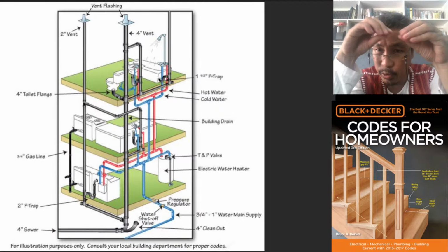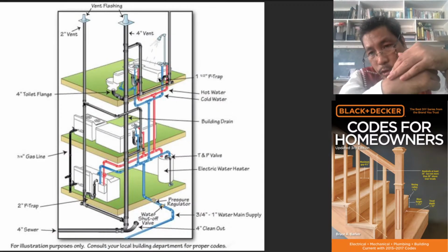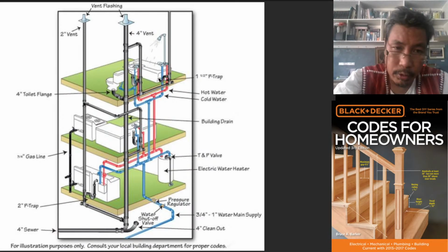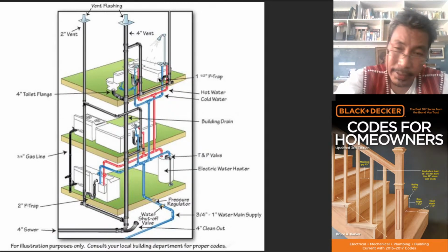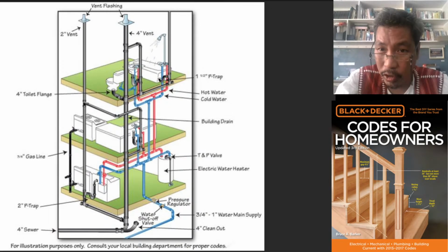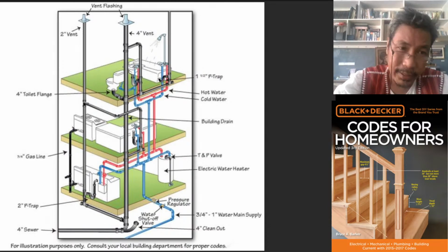We need to use sealant, rubber or plastic seals, so that the water would not be able to get inside the interior parts of the building. Now, flashing is one method in order to avoid water coming inside the building. That is what we call flashing.